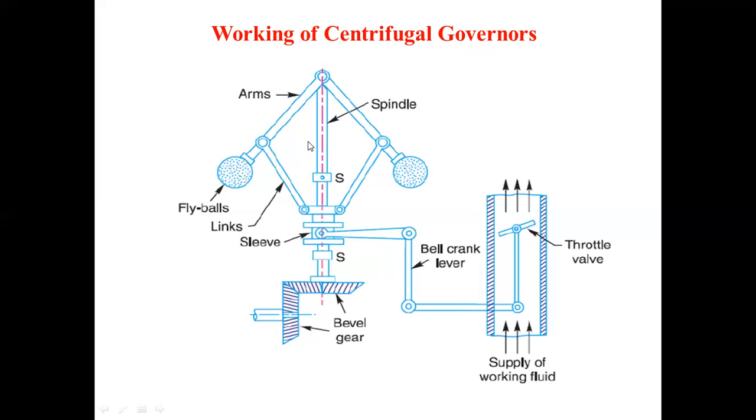Coming to the working of the centrifugal governor: when the speed increases, as I told you earlier in the function of the governor in the previous slide, these fly balls will fly outside because of the centrifugal force acting on them. The sleeve will move upward.